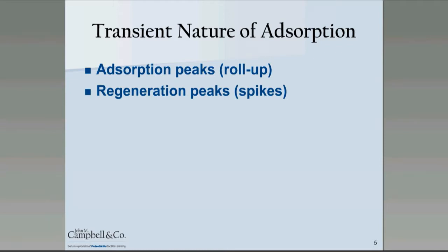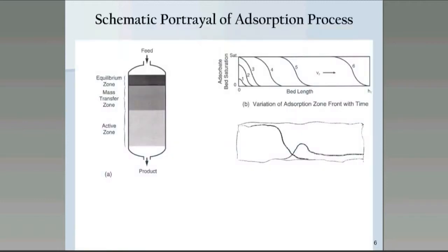The takeaway message from this simple slide is adsorption is not steady state. It is a transient process. This shows a schematic picture of what we just described with respect to components, weakly held components, loading up on the active portion of a molecular sieve bed. Here we see a molecular sieve bed with three zones that are established during the adsorption.